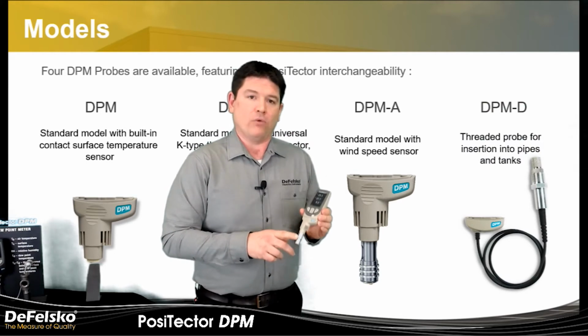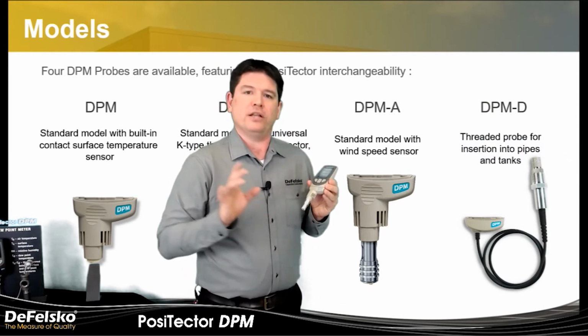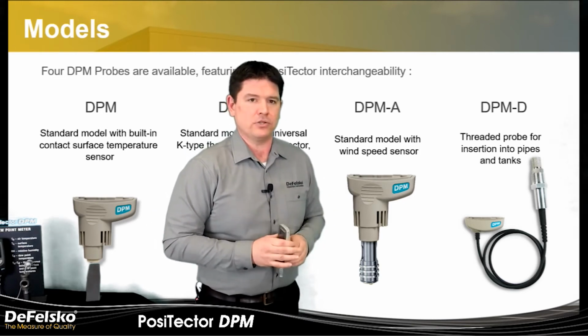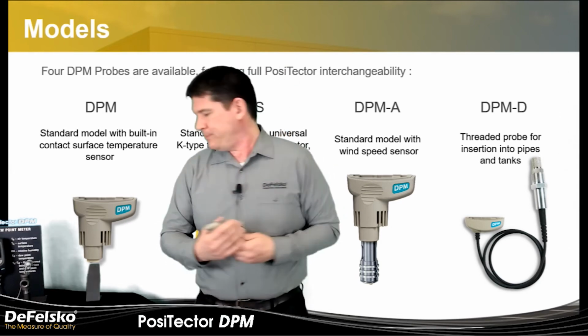That is a very sensitive wire. If you do get any dirt or anything in there, you can blow on there gently to clean it out, but we do not recommend sticking anything in there because it can damage that sensor. If that does happen, please send it in to us. We can clean that up for you.